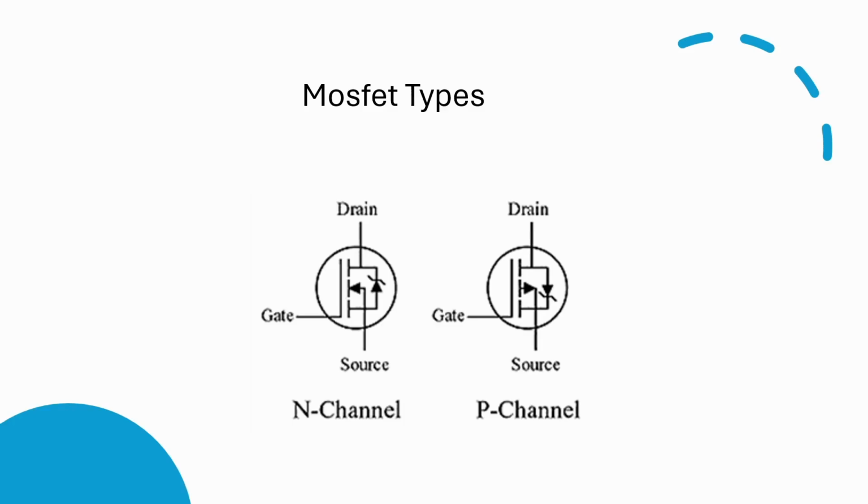Each MOSFET has its own specifications and ratings. We will be focusing on logic level FETs today, meaning you can switch them on and off with low level logic, which is exactly what microcontrollers output. And depending on the chipset, it's somewhere roughly between 3.3 to 5 volts.